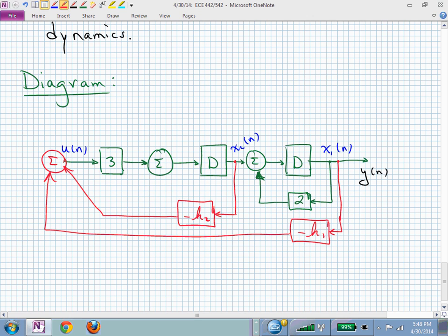The full state feedback simply means that you are accessing every one of the state variable components, x1, x2, and if it was 4th order, x3, x4, feeding those back with an independent gain value. This now interconnected system allows us to change the dynamic behavior. Is that clear?